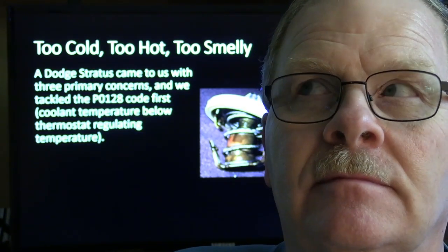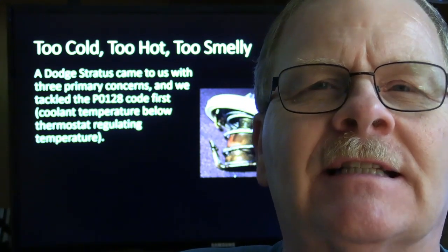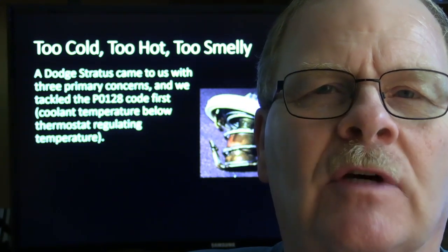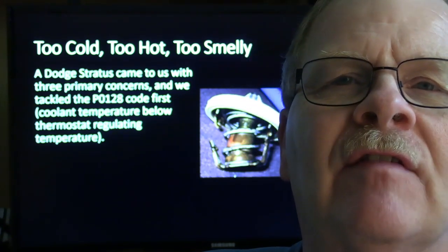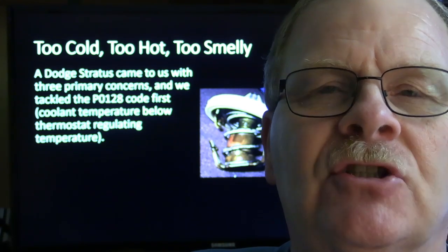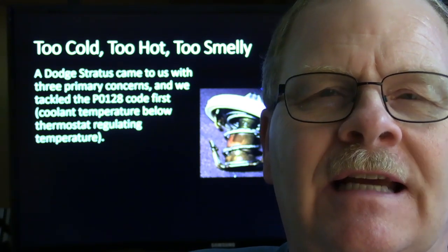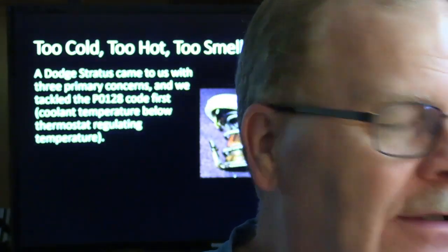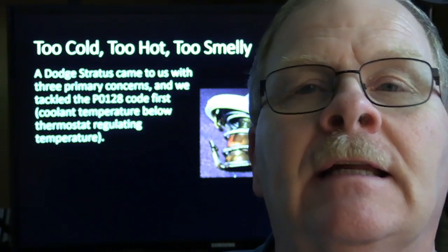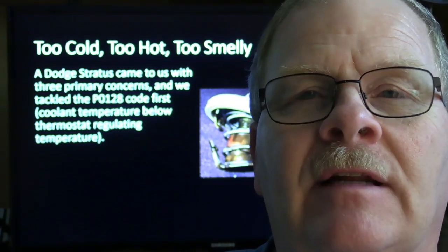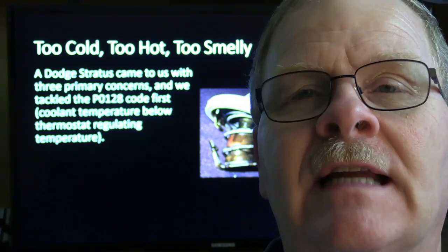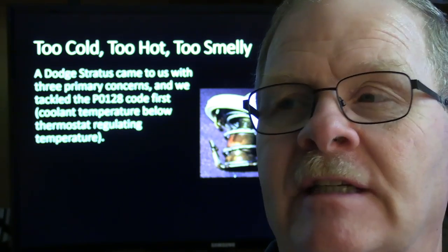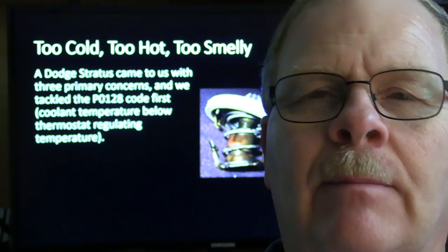Now, there are occasional exceptions to this. For example, if you've got a late 90s Toyota, like a Camry, that's throwing you a P0125, then the oxygen sensor heater can actually cause it to throw that code because it's taking too long for it to drop into closed loop fuel control. And there's an algorithm apparently that's typed in there. The reason I know that is because my son was driving a 1998 Camry for a while, and he lives about 6 hours from here, and he was calling me and said it kept throwing that code.